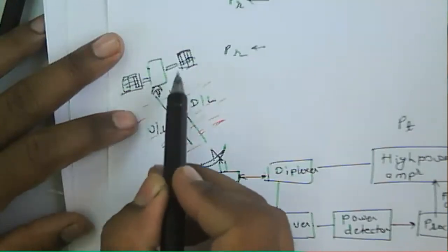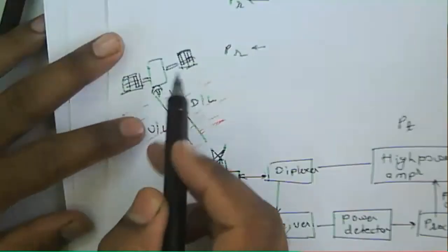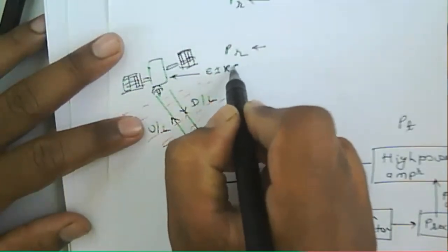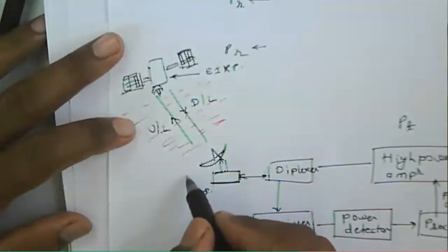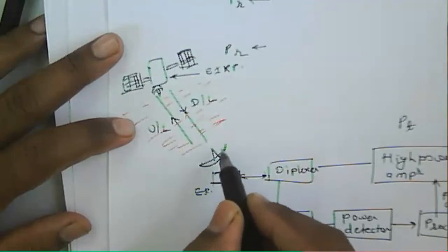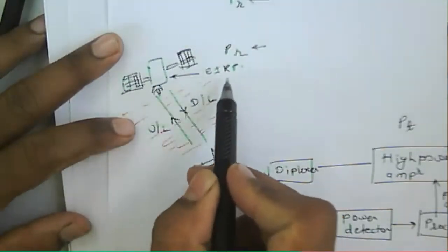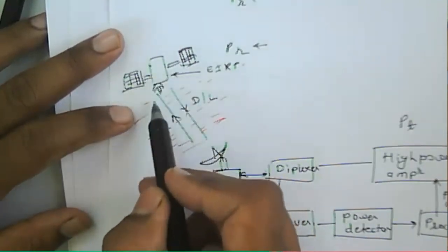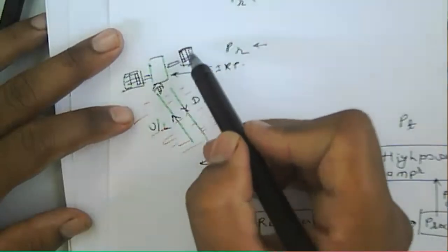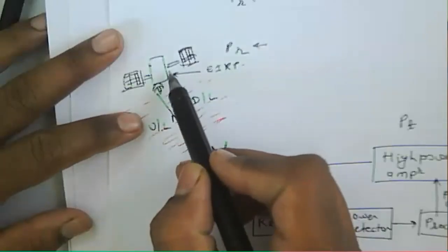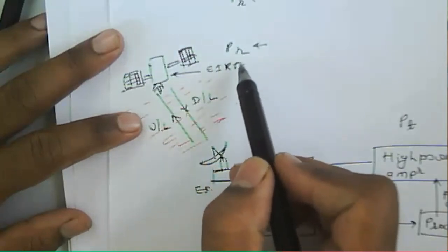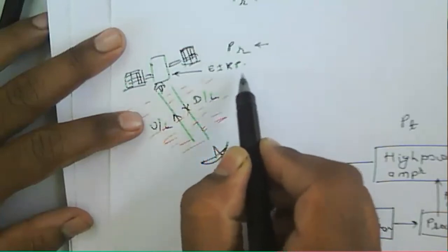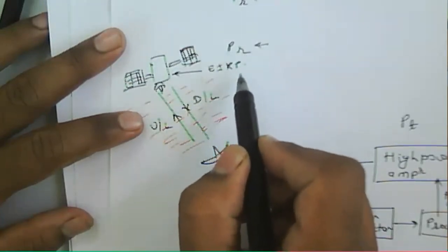So when the transponder generates the high power at the transmitting station, which is the satellite, we can increase the EIRP. For the uplink, we need to increase the EIRP at the earth station. For the downlink signal, we need to increase the EIRP at the satellite. Because there are different modes, high power mode and low power mode, in a transponder, it may be easily switched from the low power mode to the high power mode. So switching takes place for the desired EIRP.